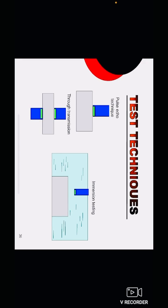These are the types. The pulse echo technique is the first one, and immersion testing is used in a wider area. In through transmission, the sound can be passed through the object. In the pulse echo technique, the echo stays in the upper area, but in through transmission it passes through the object.